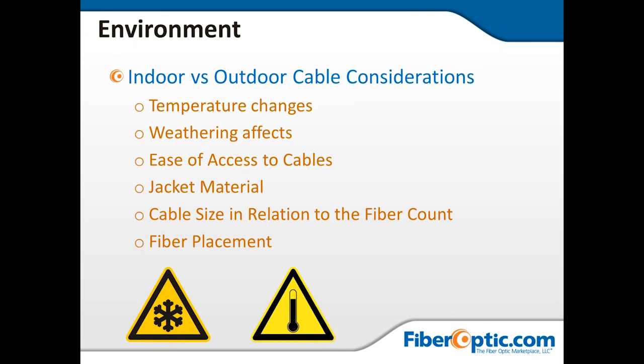And then you're going to look at fiber placement. How deep are you going to go? Where are you going to place it? Looking at your manhole locations, pull box locations, splice locations, all of this to make it easy to get to and work on. Just because it looks good on a map doesn't mean it looks good in the field.